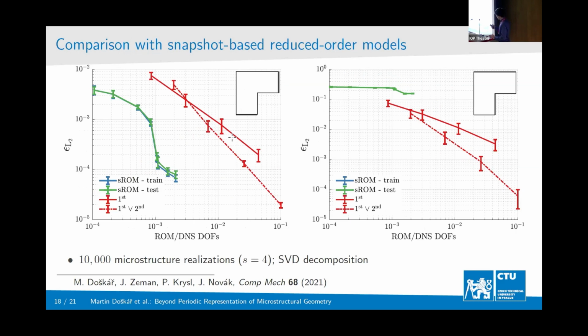But now, if you have ever worked with reduced order modeling, then you might say, but the reduction is not that great. With standard reduced order modeling, you can do much better. And you are right. But the difference here is that in standard snapshot-based reduced order modeling, you have your macroscopic domain, your loading, and then you start with certain parameters. You compute several snapshots, and from those snapshots, you compute eigenmodes with the highest eigenvalues, and you plug them in as your basis functions. And basis functions constructed in this way are very specific to that problem.